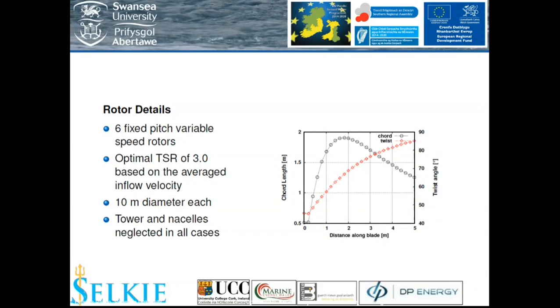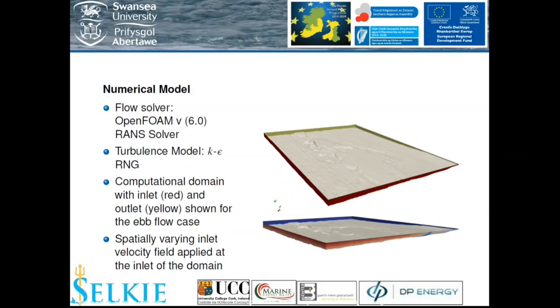An explicit grid layout is required for use with the GAD-CFD technique. Thus, a blade box must be defined. The blade box represents a rotor of 10 meters in diameter with length of the box in the flow-wise direction fixed at 0.1 D. The chord length and twist angle characteristics of the blade are presented on the right image. These profiles are used to determine the occupation of the blades over the blade box region to determine the exact location of the blade forces.